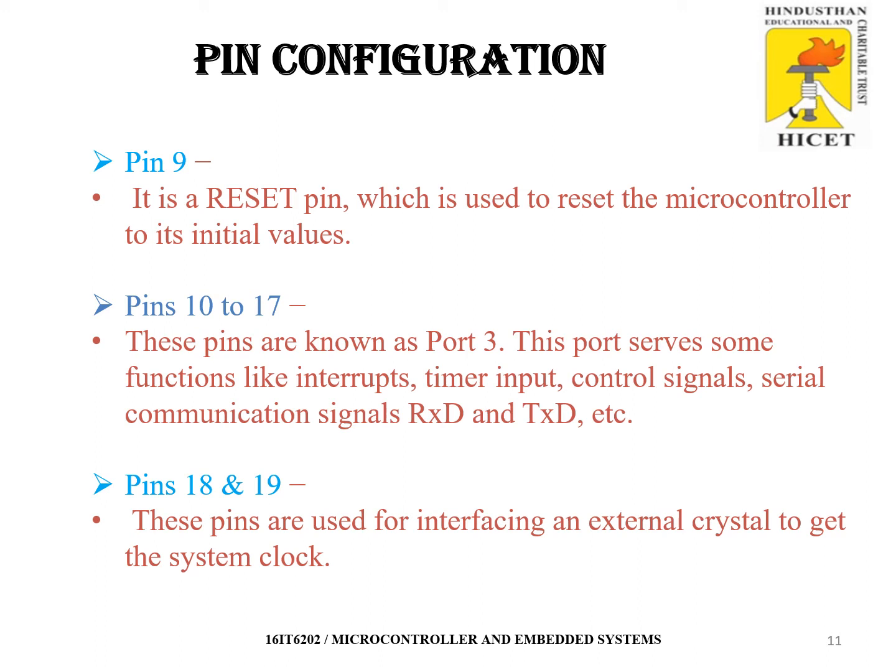Whenever it is high, the write operations cannot be executed. The next pin is RD bar. It stands for the read operations. These read operations can be taken at port 3.7. Then you have RxD and TxD. The microcontroller can receive signals and transmit signals. RxD stands for the receiver and TxD stands for the transmitter.